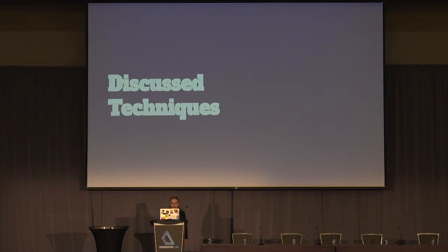And then also not pictured in these slides is the SOC or IC implants. Most modern processors have many, many cores inside of a single chip. So in fact, the integrated circuit or the IC chip, on cell phones especially, has everything the device needs. So it has USB, audio, video, Ethernet, memory cards, and they're all handled on one chip, not pictured here. And obviously the cost of performing this type of intentional backdoor is much higher.